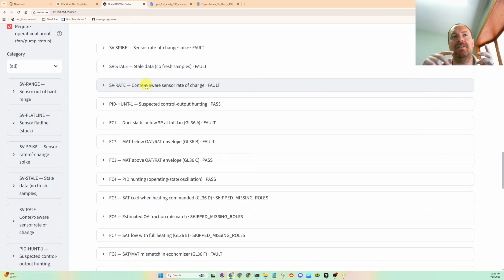There could be leaving air temperature after a DX cooling coil or a gas burner or a chiller, so different sensors have expected or allowable rates of change. That's all getting baked in here, except I need to beef up how I'm reporting on this as well.